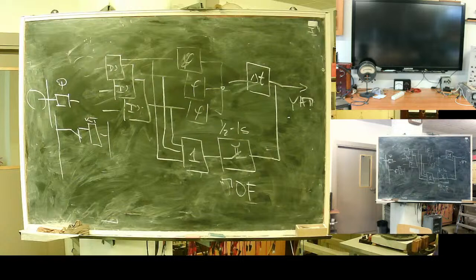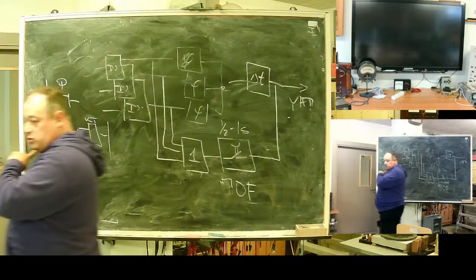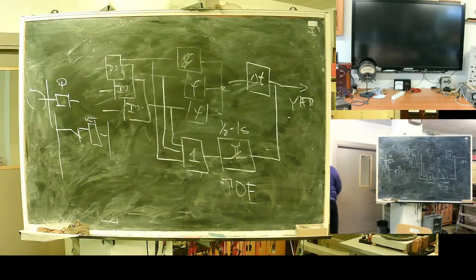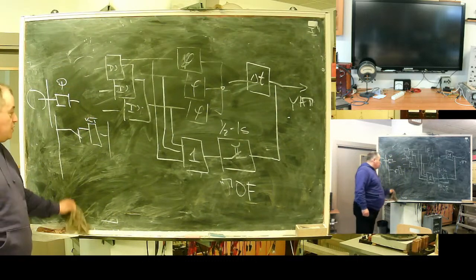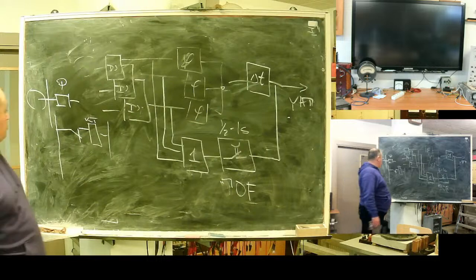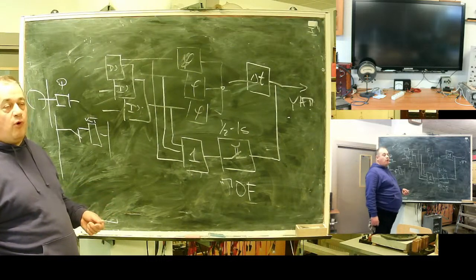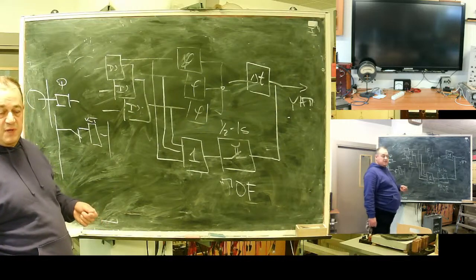This bypass network is for switch on fault scenario. It's an older version. For the newer version, the so-called non-selective, actually in terminology, there is speed up before and speed up after.